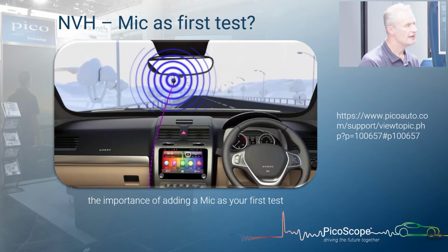But ultimately, having an accelerometer will capture all those low frequencies, and having a microphone will capture all the high frequencies. And there's also the beneficial side effect here of being able to narrate your road tests. Whilst you're in the cabin, you could be talking, it will be recorded. You could mention that you're steering left or you're braking. All that will come through in your recorded capture.